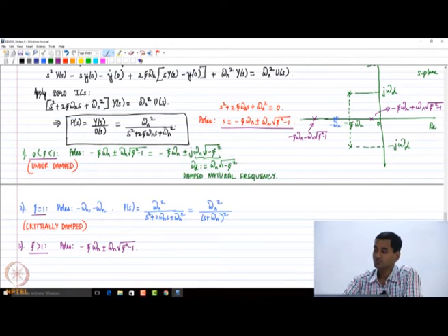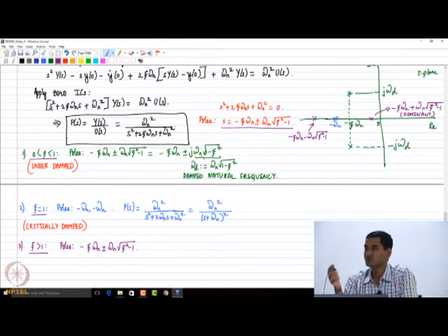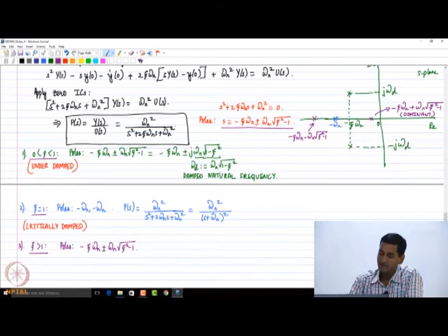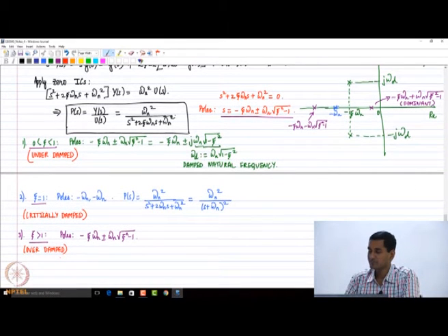So as a result, this one is the dominant pole, okay? Please remember our definition of dominant poles, right? The pole which is closer to the origin is what is called a dominant pole. Such a scenario where zeta is greater than 1 and we have two distinct poles on the negative real axis corresponds to what is called an overdamped case, okay? So that's the overdamped case.